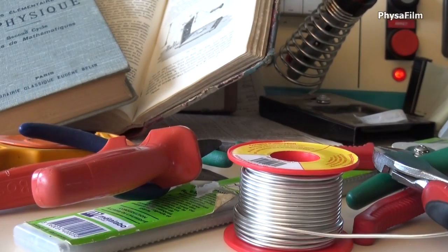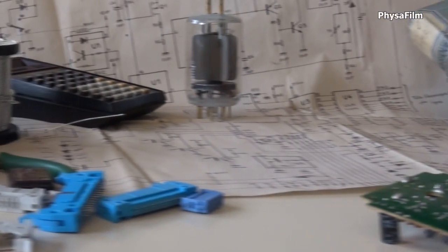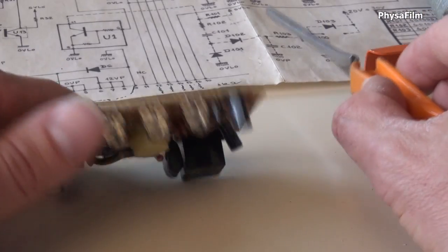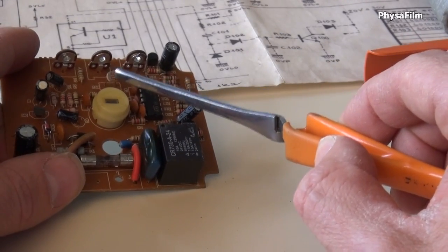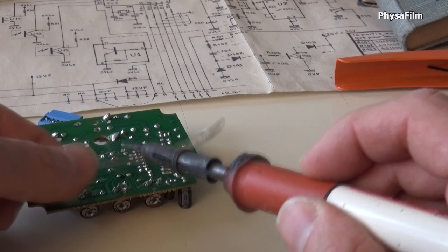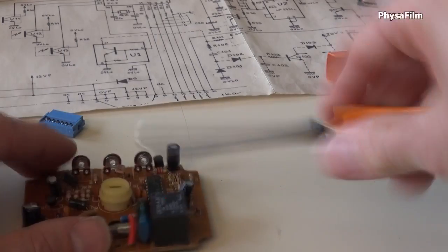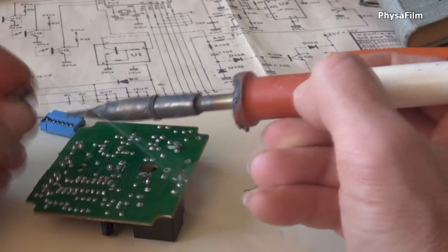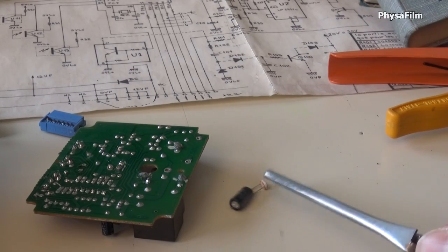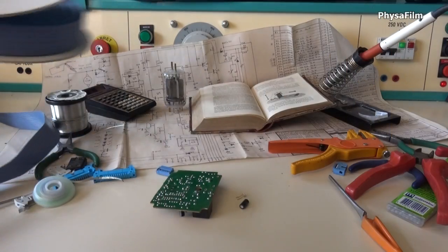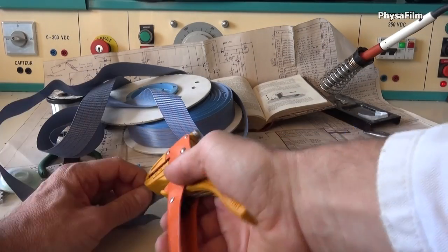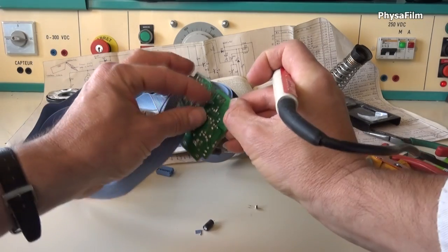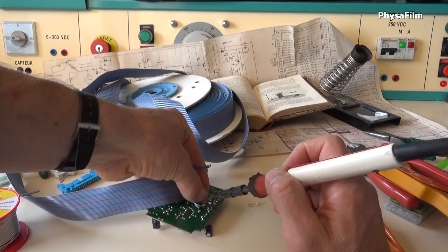We gather all the technical equipment we need to alter the structure of the control board electrically. We locate on the circuit diagram and then on the board the electronic components behind the disorganized and random sequencing of the wave generator. We unsolder these components to neutralize them. Now we connect a bundle of multi-stranded electric wire to the board so we can command and take control of the oven's generator using a remote computer system.